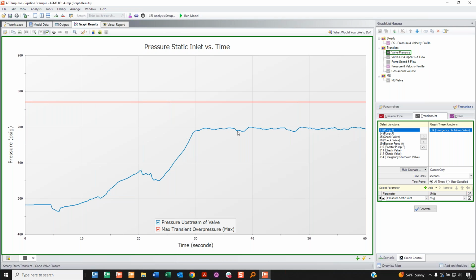And I would say yes, but remember, you have to still worry about the idea of the controlling CV and the fact that the first part of the valve closure pretty much does nothing. So that's why I did the stage approach, to make sure it's not just that I extended it to 30 seconds, it's also that I did it in a different way. So anyway, you might need to rewatch this a couple times to capture it. I know it's a lot of information, very dense.